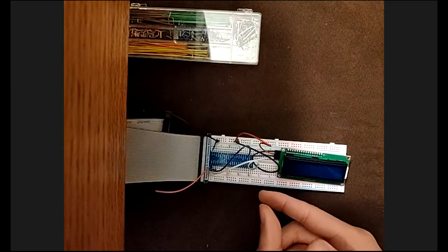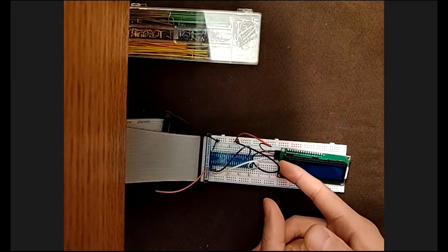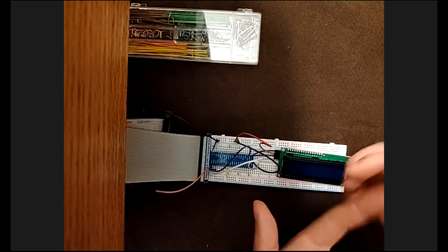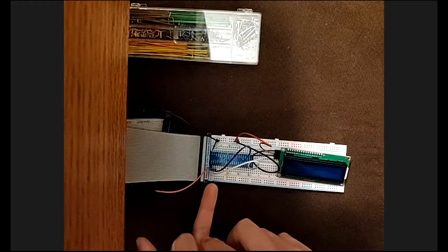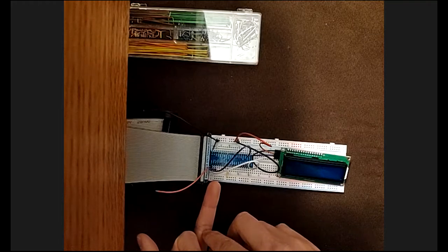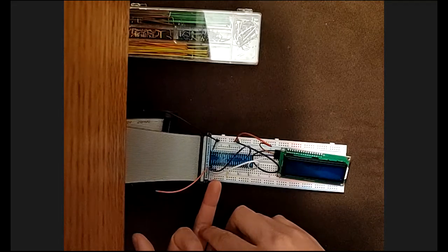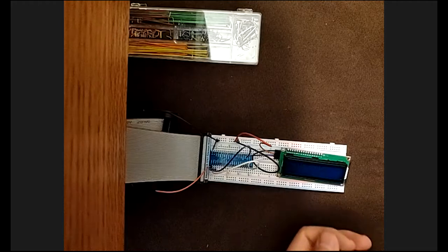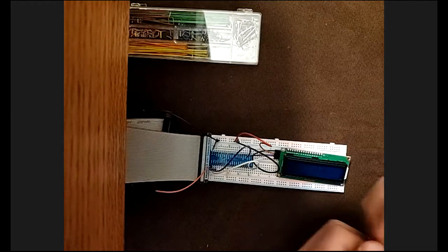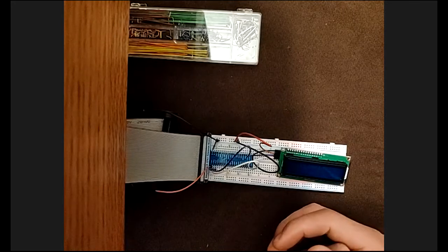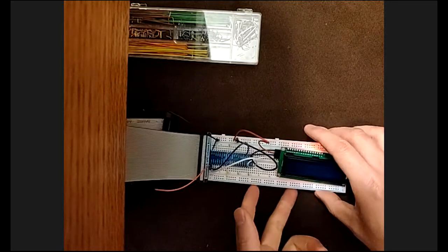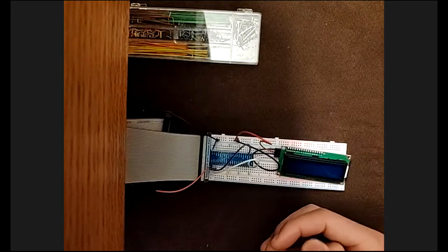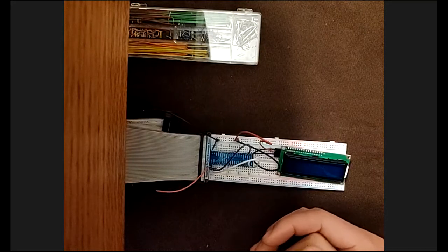So that's it. There's basically just 4 cables to connect. You got a ground, you got a 5 volt, and then you have 2 data cables that go to the SDA1 and SCL1 pins. Those are at the top left corner. Okay. And when you're connecting cables, just always be extra careful not to connect to the wrong places. Those holes are pretty small on the breadboard, but just pay attention to details.